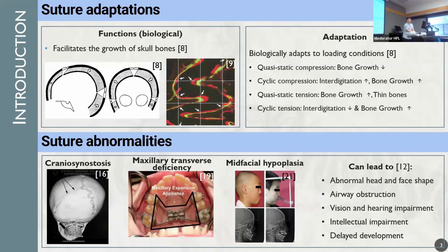Yeah. So for this study, next step will be considering fiber orientation and considering more advanced model or material type. Also in this case, since it's quasi-static, I'm not really considering viscosity, but actually suture is also viscous and with different load rate behaves differently. So on this project, next steps will consider all that.